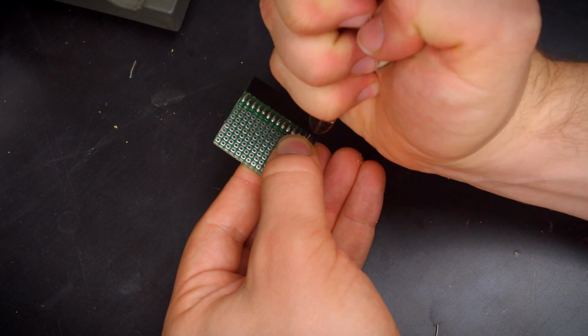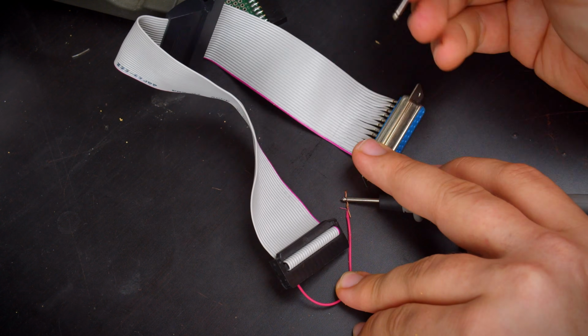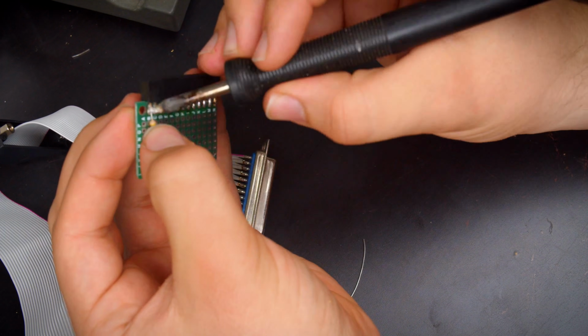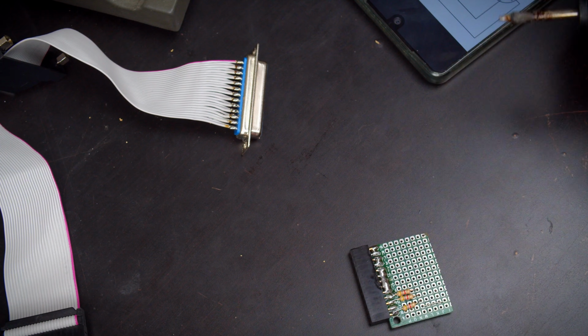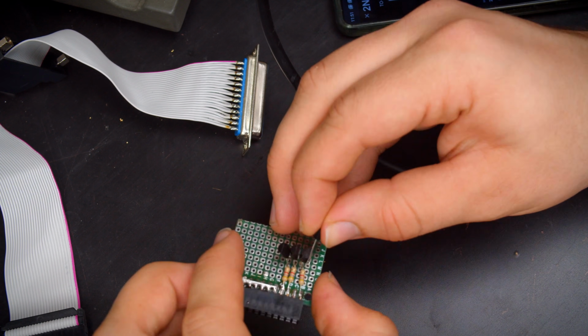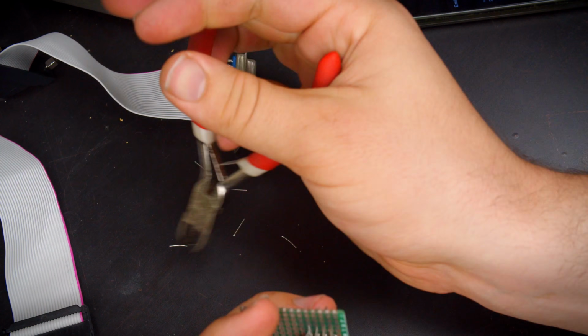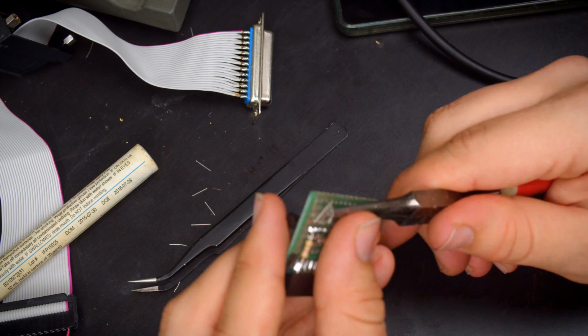At this point, I'd like to point out that all of the pages I've seen online about how to make one of these tell you to use a BSV52 NPN transistor for this. I think this goes back to one of the first versions of this adapter that was sold as a single circuit board with 2 connectors on it, because there's no real reason you need to use that particular transistor, and being SMD, it just makes life harder.